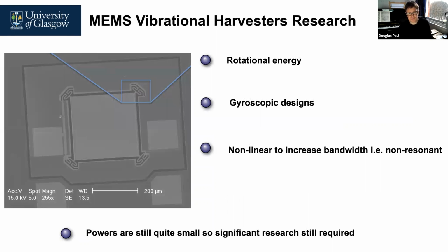Now, this is a field where there's still an enormous amount of research going on, both in universities and definitely in different companies in this space. I've shown you typical systems that are out there. Some of the real problems is that at the moment, all the commercial systems really only vibrate in one dimension. What I mean by that is that they're only extracting energy from vibrating systems that go up and down or travel in 1D. There are many examples where you could potentially improve the amount of energy you can extract if you could extract in multiple directions.